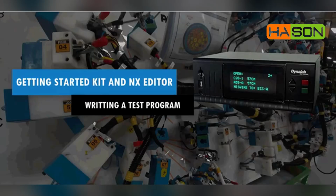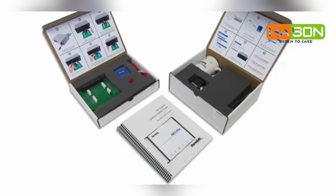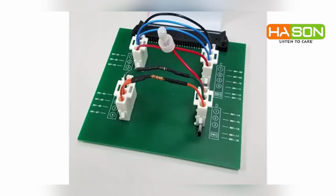We will use the tutorial wire harness and fixture that are provided as part of the Getting Started kit. If you recently purchased your first NX tester, you should have received the Getting Started kit in the same shipment as the tester. This is the tutorial wire harness and fixture. The tutorial wire harness contains an example of several common elements found in production wire harnesses, and it helps to demonstrate the NX editor's features for programming the different components and elements.